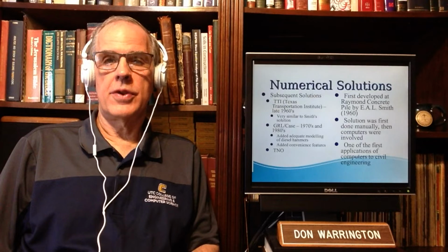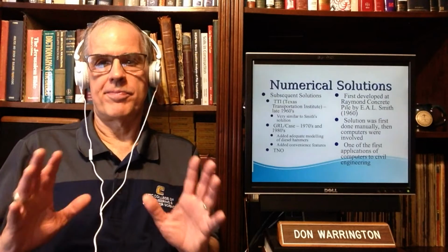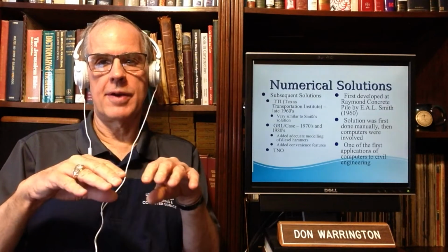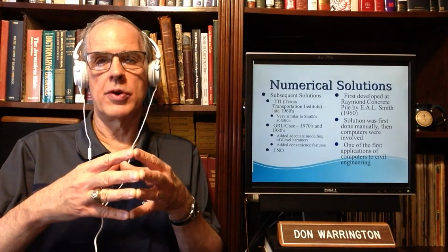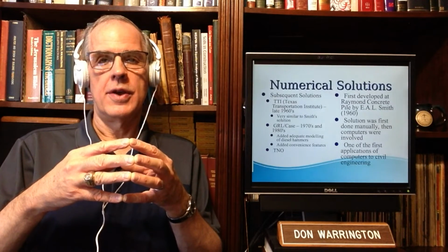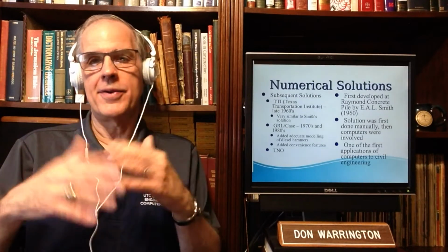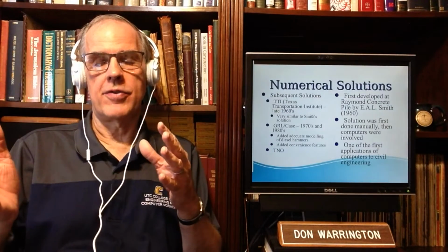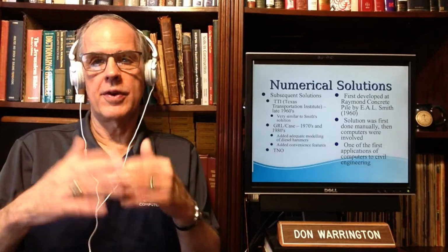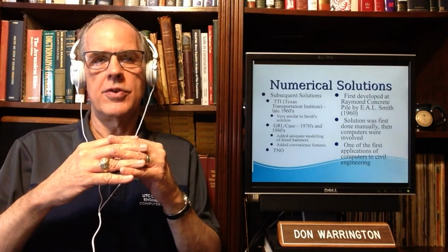However, there were two major building blocks missing from the TTI solution. One of them was the modeling of the diesel hammers, which were becoming more popular, particularly for onshore applications. And the other one was an inverse method. In other words, if you had data from the field, you could take the wave equation and play around with it until you get something that looks right. You can still do it this way, but that's not necessarily the best way to do this.